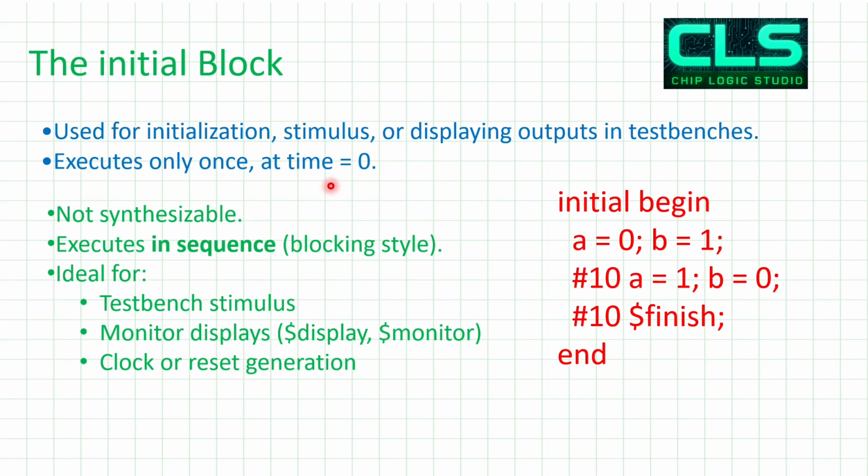As I said earlier, at zero simulation time, at the start of simulation, it will initialize or give some values. Here you can see code for a simple initial block: a equals 0, as we initialize this, and we can use delays and $finish statements in this initial block. For example, if you write $finish at 10 nanoseconds, or 10 units of time, it should execute once.